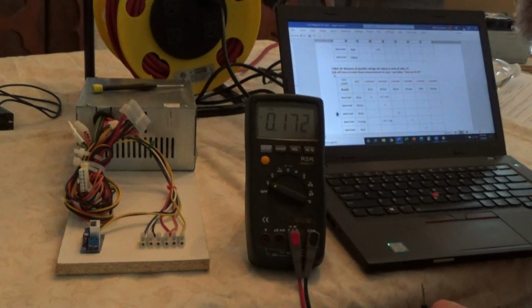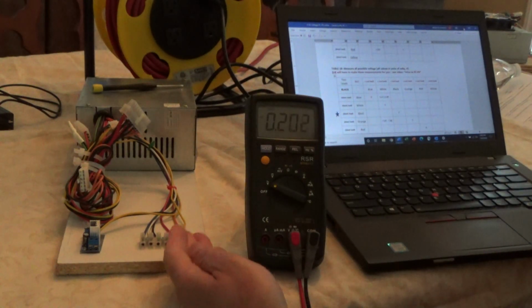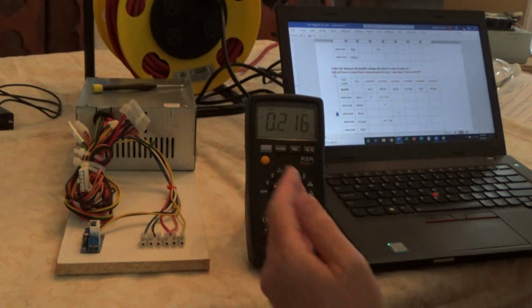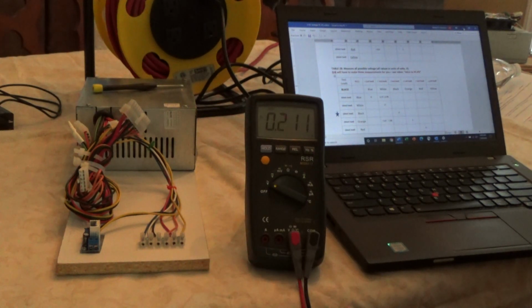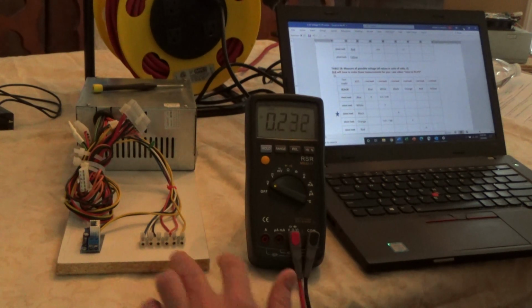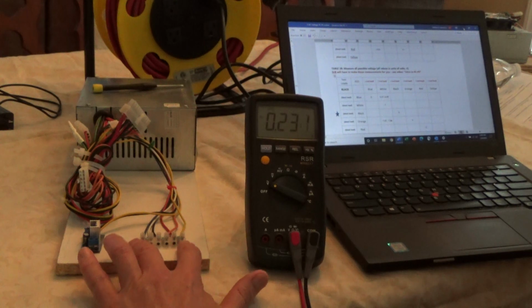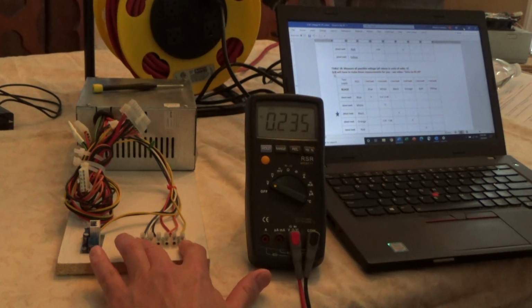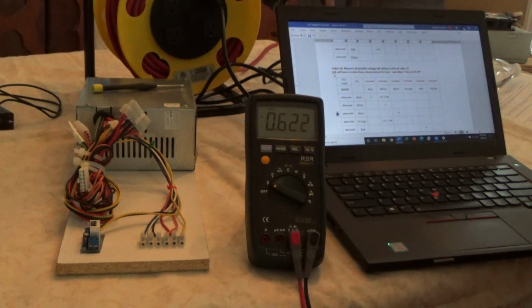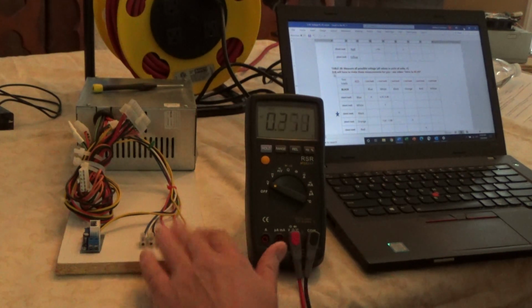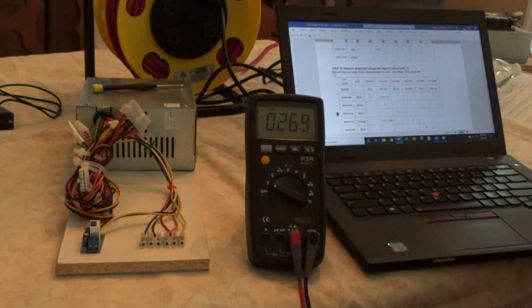And if you think about it, these are very, very useful voltage values because when you buy a computer, it's got a lot of common electronic elements in it. For instance, you're going to need a plus and minus 12 volt rail to power a bipolar op amp, an operational amplifier, and your integrated circuits and things like that. These are very popular voltage rails for various electronic components.